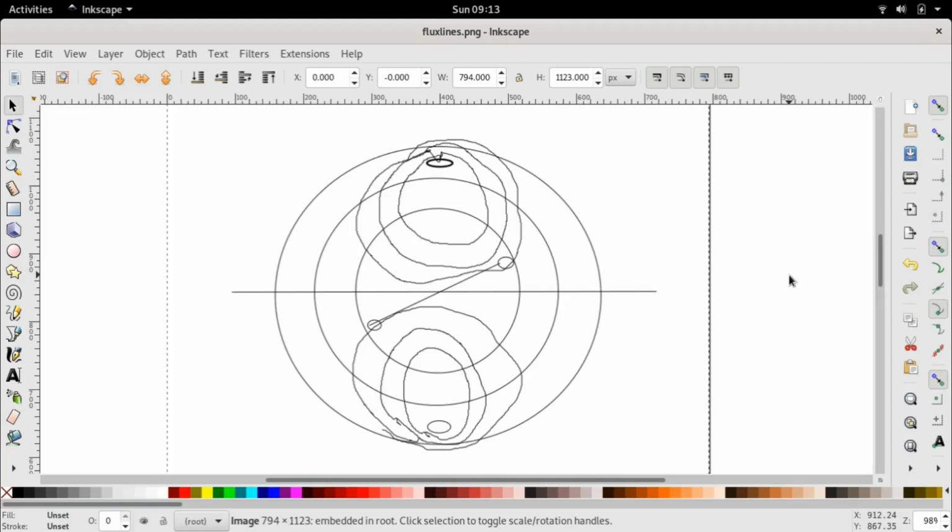Hello everyone and welcome back to this next lecture in the machines video series. This is where we had left off last week, where we had drawn the flux diagram for a cylindrical rotor induction motor. In this case I had represented both the stator and the rotor windings in the most simplified form of just two slots diametrically opposite each other, and all the windings passing through these slots.